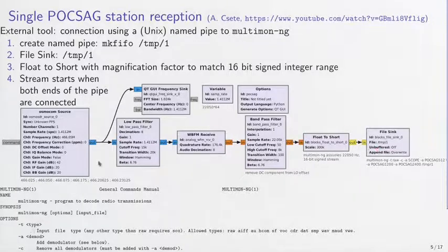So once we understand how to decode one multimon instance of a POCSAG single channel, then we've seen that there are at least 6 channels that are active. We've seen 4 of them in the prior spectrum. So now we can just duplicate, this is the power of software-defined radio, adding more channels that do not require taking the soldering iron out and analyzing the performance of a new hardware implementation of new reception channels. We just need to copy paste all these channels, replacing the first low pass filter with frequency translating FIR filter instances.